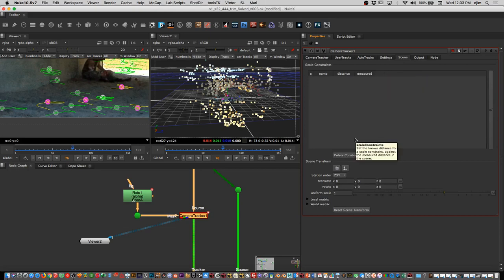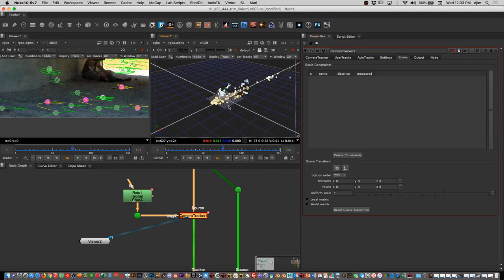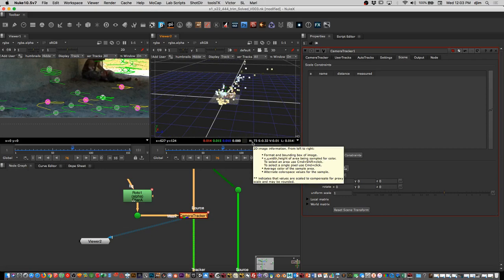In order to do this, there's a couple of things that I'm missing. One, look at the scale of the scene. It's tiny. One of those blue grid units is actually 1 centimeter, and this is smaller than 1 centimeter. So if we decide to send this to Maya to do modeling or whatever, we're going to have a hard time because Maya has far clipping planes and near clipping planes. If you try to model in a unit less than 1 centimeter, it's going to clip every time. It's not going to let you see what is close to you. A lot of people always have that issue and see the camera cutting their model. It's because they're modeling tinier than 1 centimeter. So we want to make sure that we have at least some scale.